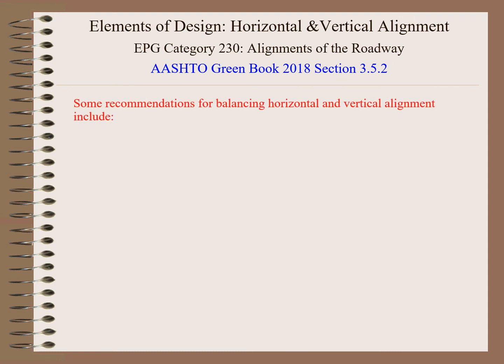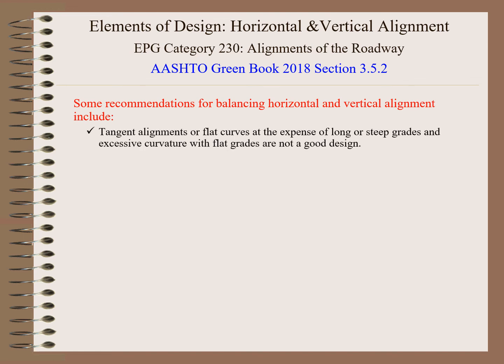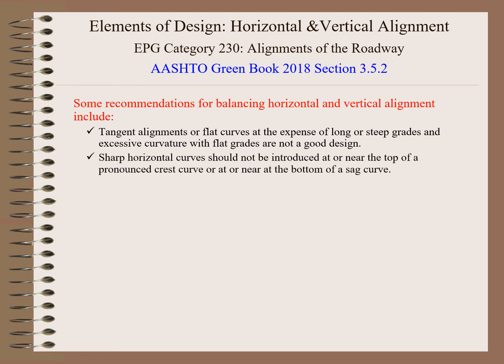Some recommendations for balancing horizontal and vertical alignments include tangent alignments or flat curves at the expense of long or steep grades, and excessive curvature with flat grades is not a good design. Sharp horizontal curves should not be introduced at or near the top of a pronounced crest curve or near the bottom of a sag curve.